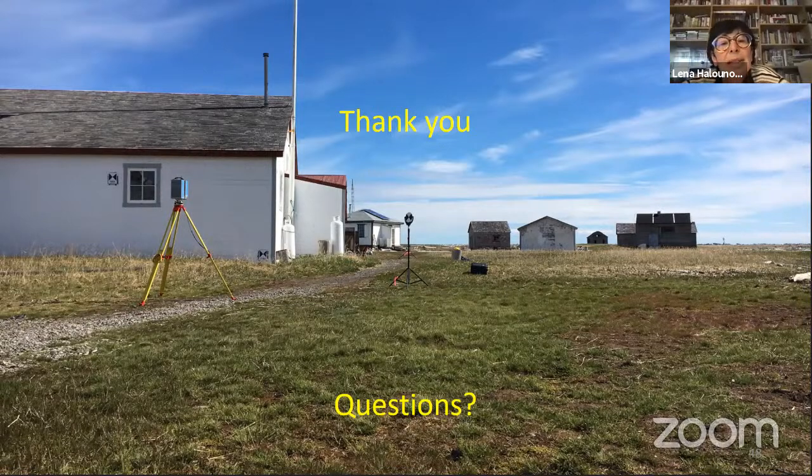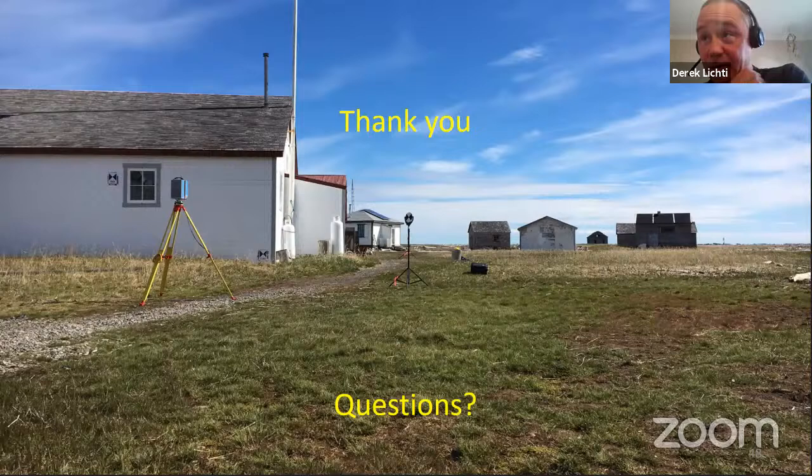From Suni Kushavaha, again, Professor, does distance from the target, angle, temperature, or target have any effect on the point reflectance, as I have faced the issue of noise due to fog when scanning at the early morning hours? Okay, well, yes, certainly the distance and the incidence angle do affect the precision, and yes, fog certainly does.